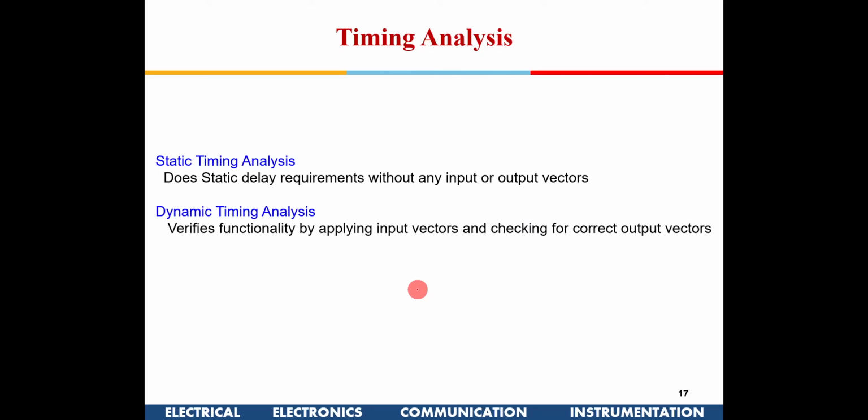We will talk in detail about static timing analysis, because there will be flip flops in between. The data needs to be presented to the flip flop a time known as setup time before the arrival of the clock itself, because if you give data along with the clock, it may not capture the exact data. Similarly, there is something known as hold time. You have given the clock, but the data cannot change immediately.